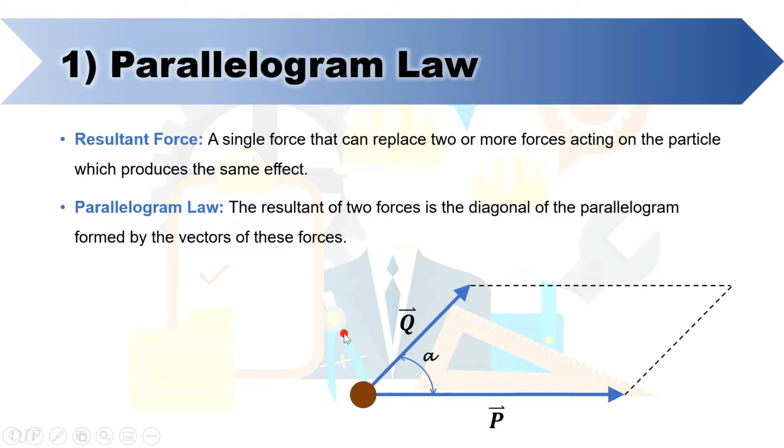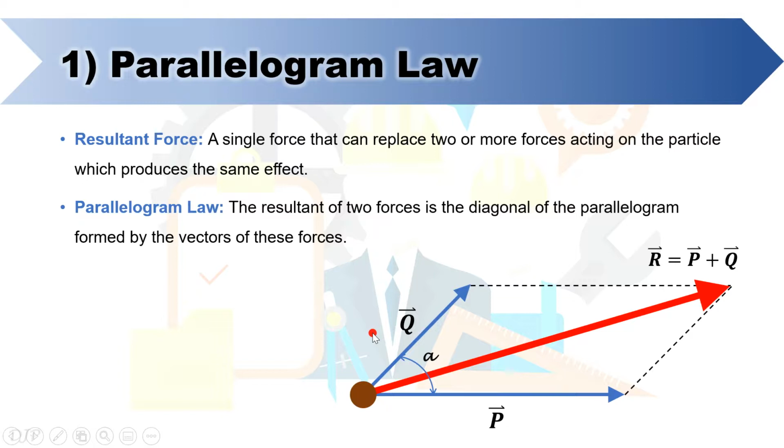The length of each force vector represents their magnitude. From here, you can draw the diagonal, which is the resultant force in this method. So you will just connect it with the tails of the given forces and the other end of the dashed lines. The length of the diagonal represents the magnitude of the resultant, while its angle of inclination describes its direction.